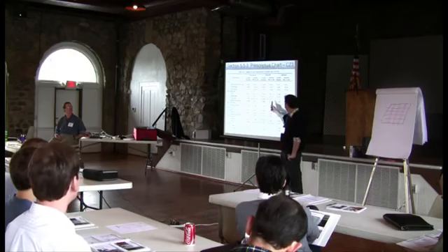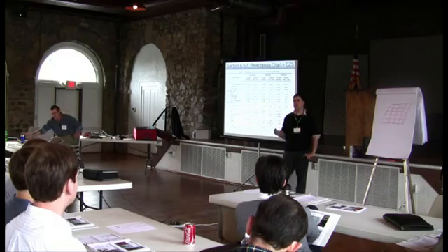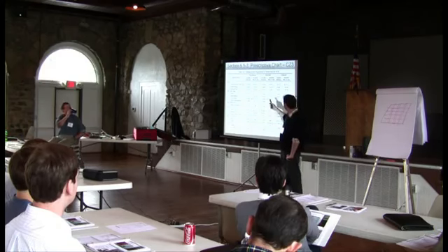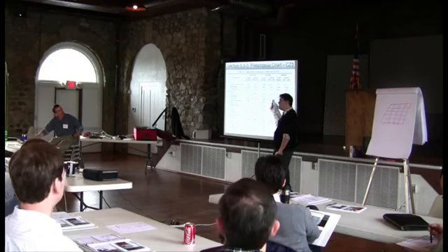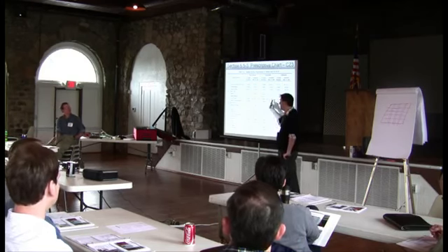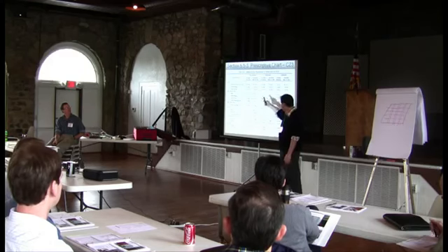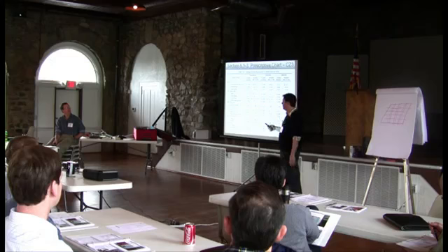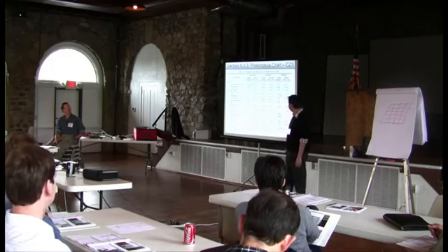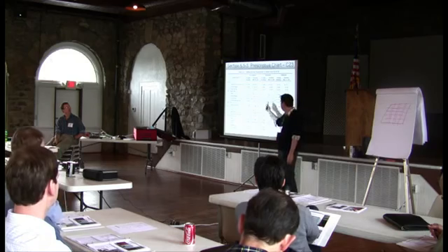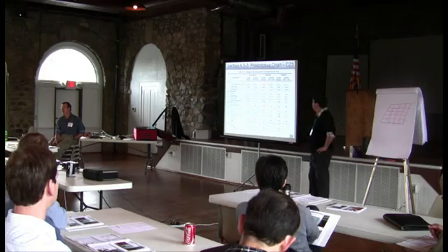Okay. I'd also like to point out, we're back to the comment that residential buildings tend to be a little more skin loaded. If you take a look over here on the steel frame, instead of an R3.8, they're asking for an R7.5, still an R13, but they're asking for more insulation. Same thing on metal buildings, the same. I guess if you have an interesting metal building, residential. Mass wall R9.5. So wood frame's still the same, but with that you get dinged on the steel and the mass wall. Any questions on that?